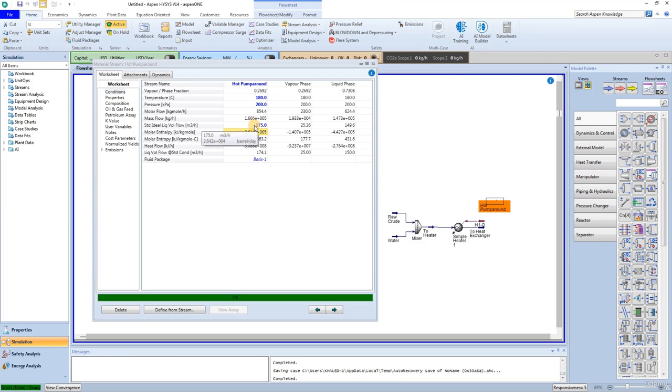A heat exchanger will be added to continue heating the crude stream. The heat exchanger performs two-sided energy and material balance calculations. The heat exchanger is capable of solving for temperatures, pressures, heat flows, including heat loss and heat leak, material stream flow rates, UA, and other heat transfer parameters.